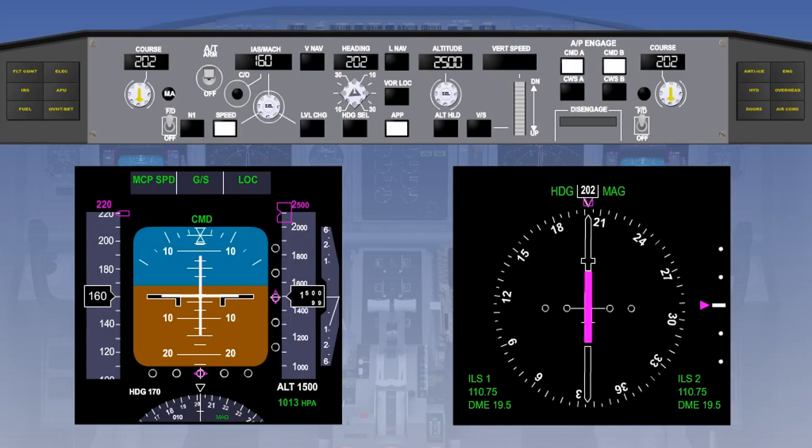When the aircraft reaches 1500 feet radio altitude, the flight control computer checks that the localizer and glide slope beams are captured. All selected autopilots are now fully engaged, and this is shown by Land 2 or Land 3 being enunciated on the primary flight display. At the same time, the flare mode will be armed in the pitch channel, and, if available, rollout will be armed in the roll channel.